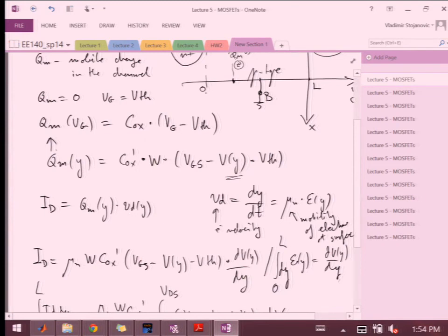In the pinch-off region, which is a very small region, you get a very high velocity crossing it because there's a lot of field applied. But I only do this integration for the time that there is actually a charge. So if this number is very big, then even though this number is very small, I'm still getting a sort of constant current.